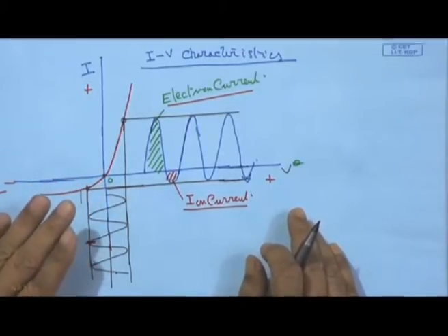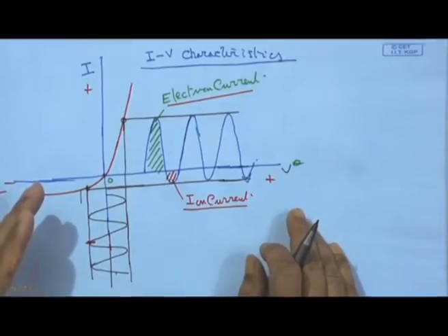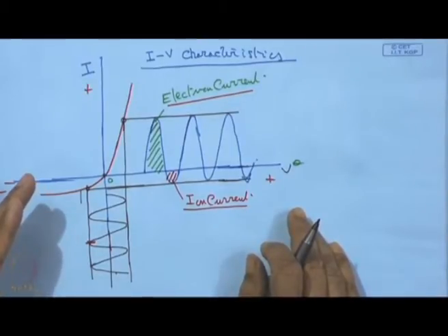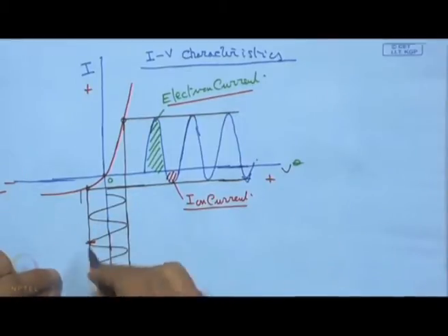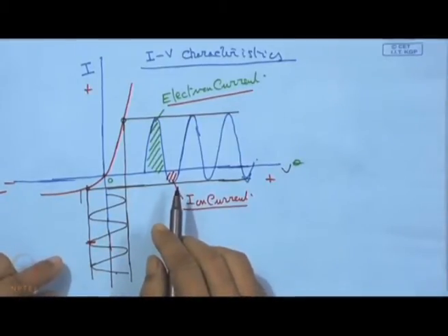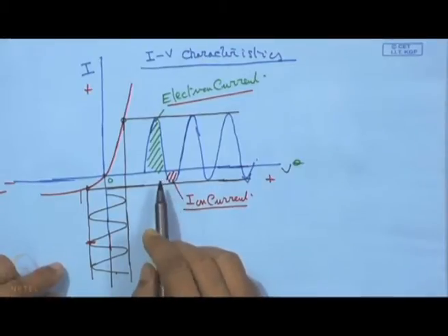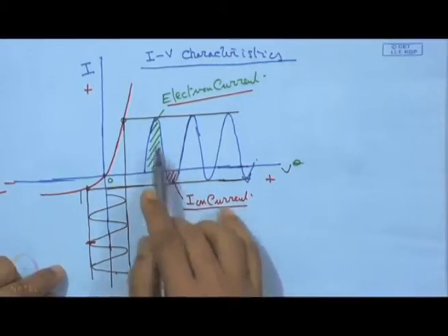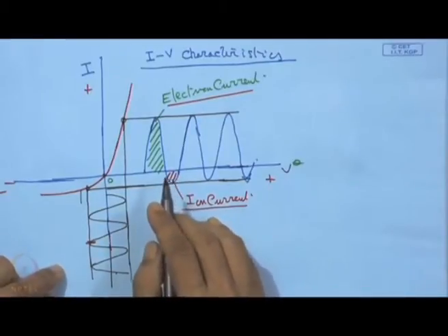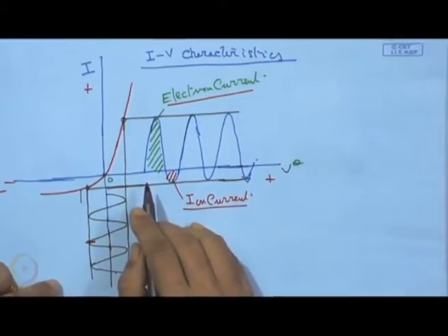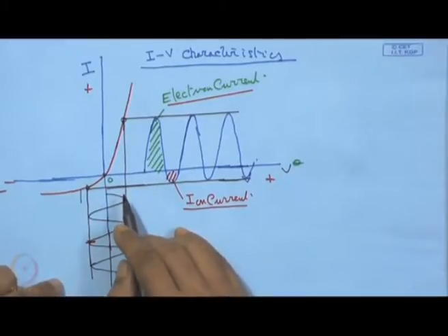But it contradicts the basic principle of a capacitance placed inside this plasma volume and subjected to an alternating supply. When it is capacitively coupled, the net current through this capacitor over one cycle must be zero. In other words, when it is an alternating supply, there cannot be any direct flow of DC current over that cycle.